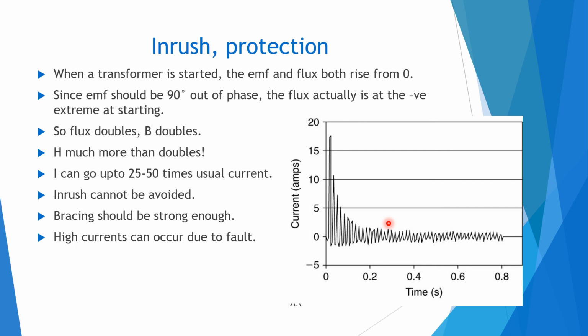So to stop that, you put protective relays which get tripped. So obviously you put the relay such that it doesn't get tripped by inrush current, but you make sure that the relay, after it senses that, like, 0.4 seconds, 0.5 seconds have gone away and there is still such a high current flowing, then the relay decides, okay, I will have to trip. So you have to design relays like that, and that's called transformer protection.